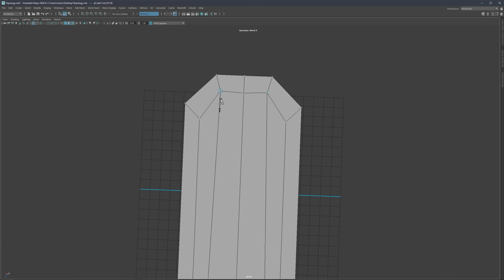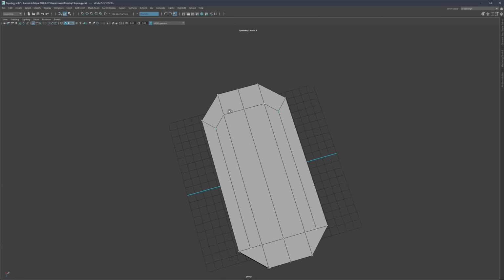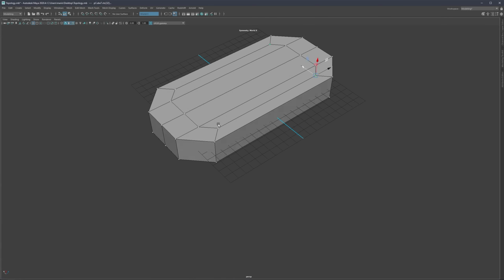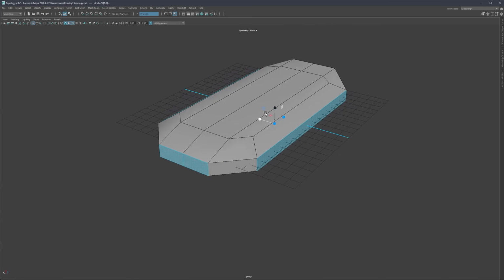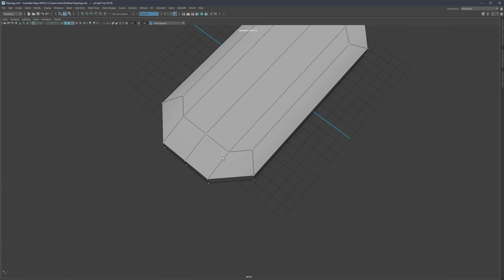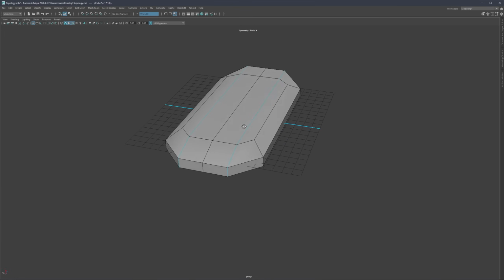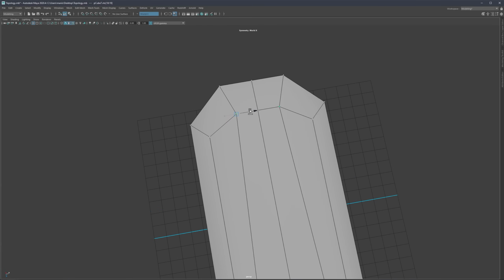But this is now the basic rules that we covered, and knowing the rules sometimes also means knowing which rules we can break and which rules we cannot. So for example, let's say that I'm making a shape here, and I need, let's say, the shape. And if I push this to the side, it's not really working for me because I actually want this. So is this still considered as a bad topology? Really not, because everything is still in place. The only thing is that the flow changes.